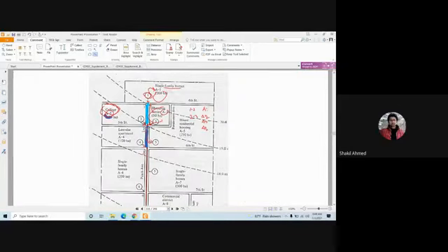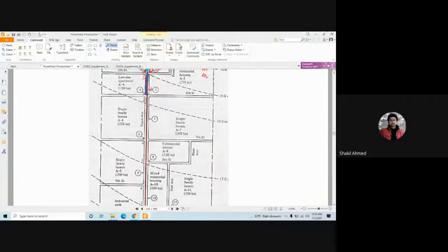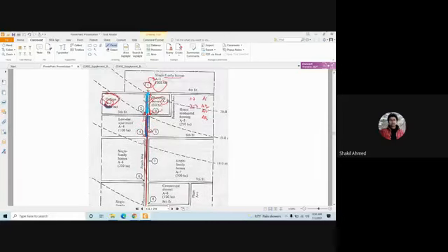this pipe 2 to 3 is going to have the contribution from A2, A3, A5, as well as the contribution from this pipe, because this pipe is flowing in this direction. Am I right? Yes, sir. So this 2 to 3 will get the contribution from pipe 1 also. Similarly, this pipe 3 to 4 is going to have the contribution from this pipe and this pipe, both.